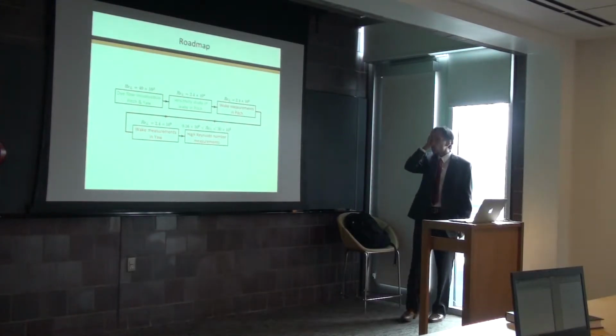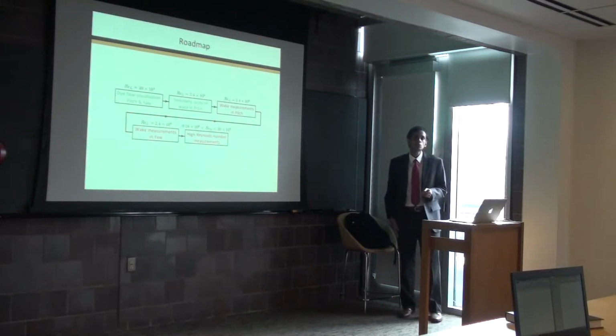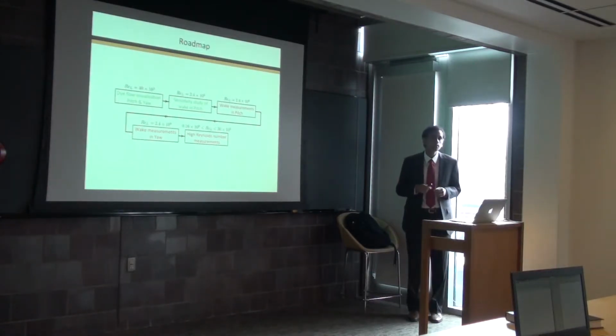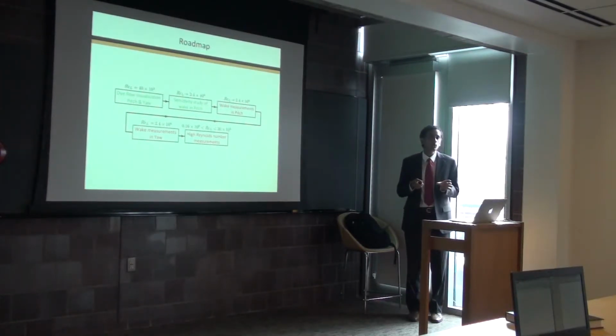So that concludes the brief sensitivity study that we have performed on the wake. It seems to suggest that free stream turbulence, surface roughness, and tripwire thickness don't result in qualitative changes in the pitched wake structure. Small yaw and roll angles move the wake around, but don't fundamentally change that asymmetry that we see.